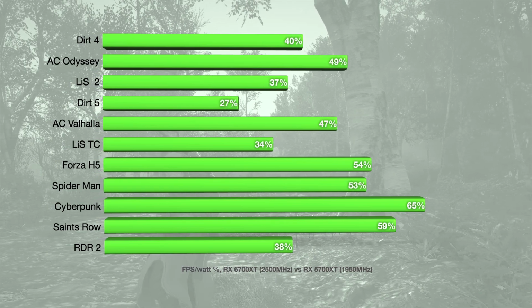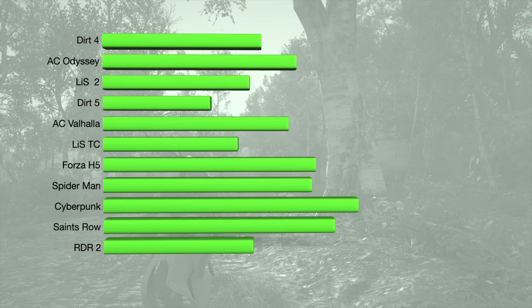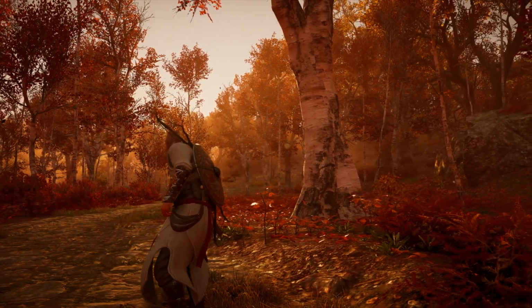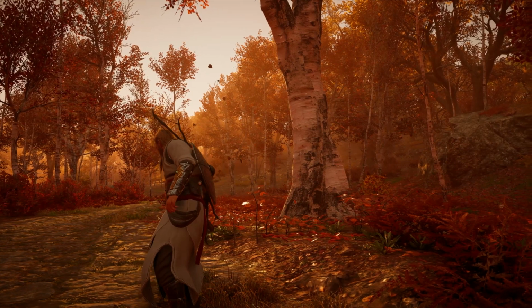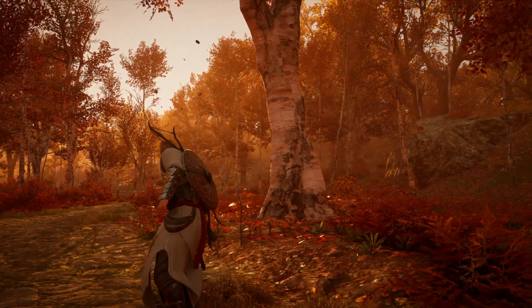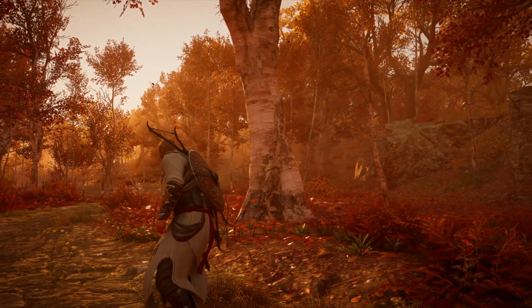But all the numbers are impressive, keeping in mind that the technology stays at the same 7nm TSMC. But remember, the purpose of this main test wasn't to compare the power efficiency. For that, we will undervolt the 5700 XT, which will leave us with a slight clock loss of around 50 MHz, but we will massively turn down the TDP.